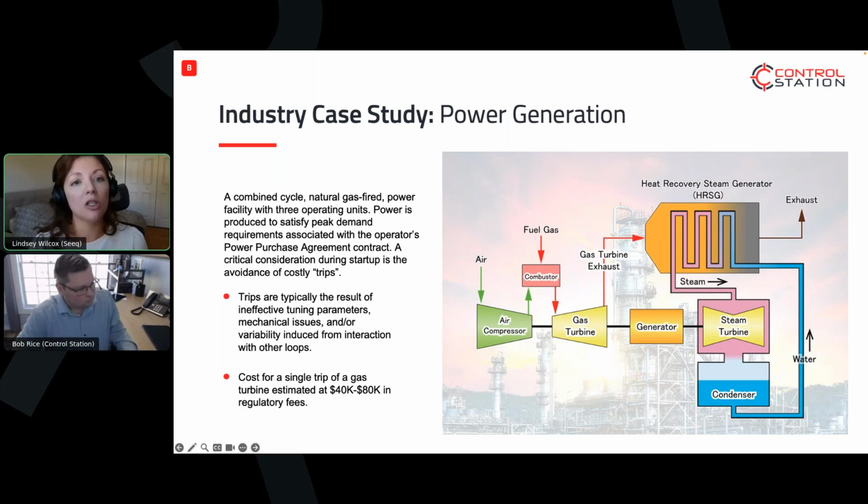So what's the overall shape of how I want that signal to look as my startup progresses? And then using that reference to build limits on what a startup should look like as good. Knowing what good looks like will help to identify deviations or drifts as the startup progresses, so that you can see them and respond to them in near real time. So hopefully you're able to avoid that trip from occurring in the first place.